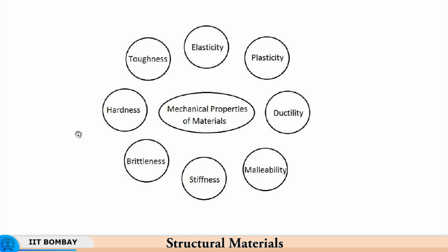Stiffness is again a structural strength. Yes, it's a structural strength. Brittleness is something that relates to durability, because brittleness gives you an idea about how well the material performs against shock loading. So brittleness and toughness are the two properties which give you an idea about the response to shock loading.